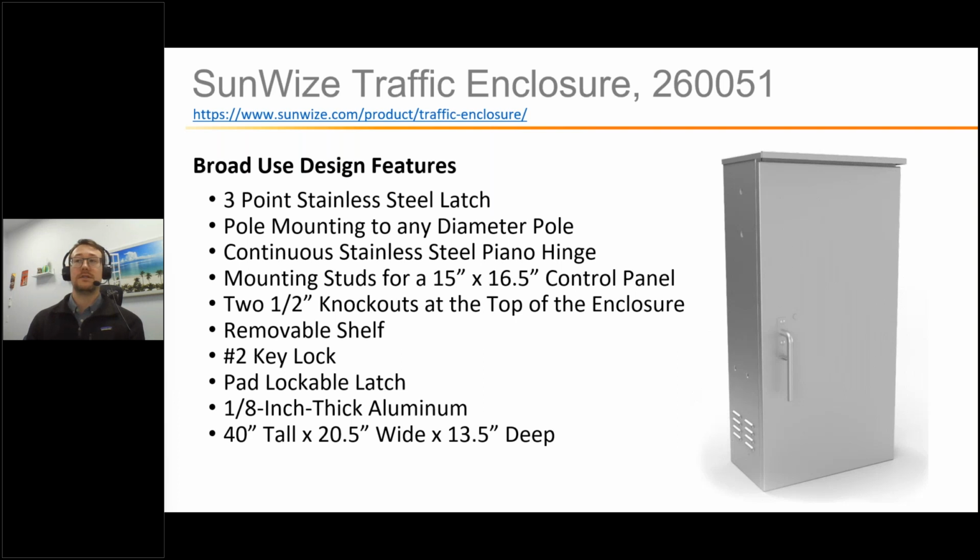Some of the biggest ones include 3-point stainless steel latching, a broad range of mounting to different pole diameters, which on a given project can be quite varied, a continuous stainless steel piano hinge, mounting studs to fit our standard control panel backplate sizes, which makes integration easy for either SunWize if doing the complete turnkey system, or for our partners if they're taking on some or even all of that integration scope of work themselves.